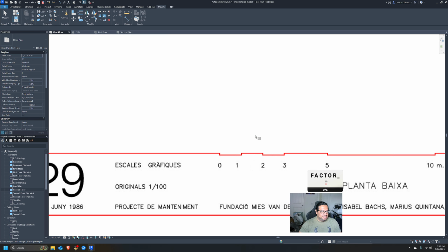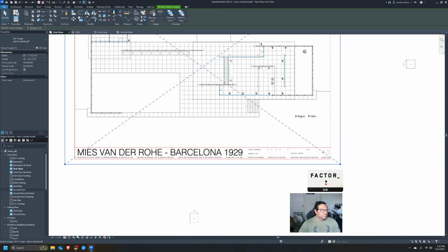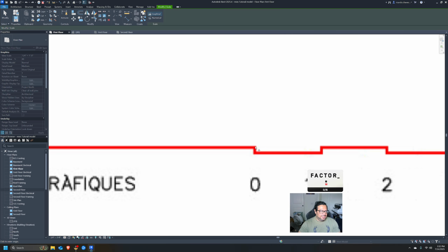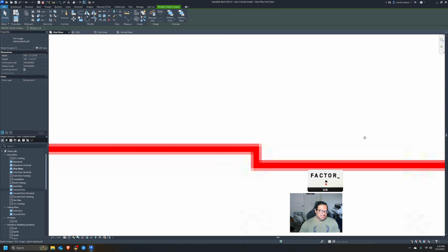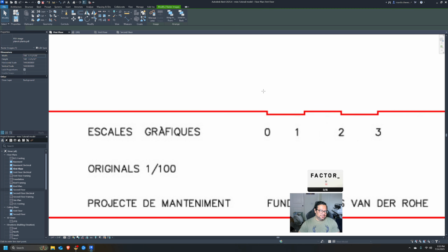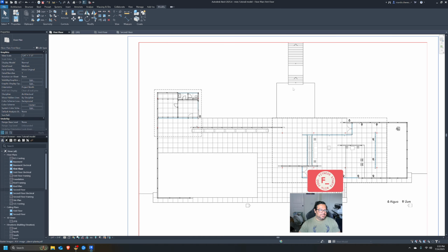So we're going to click on our image, click on Scale, and then click here, kind of in the middle, and then click here. So it's about a foot, yeah. Now it's asking us what the actual distance between these 2 points is. We know it's 3 feet. So now there's our scale drawing. And if you're ever unsure, we can draw a line, and you'll see 3 feet. So now this is the proper scale of the drawing.